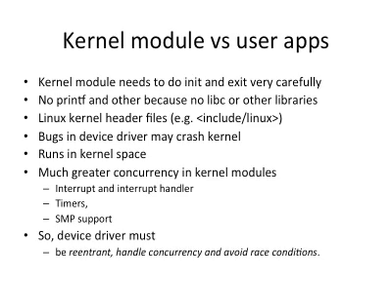So you have to be very careful when you design your init and exit functions. In fact, everywhere in your kernel driver, device driver, Linux kernel module, you have to be careful, especially with space allocation, memory space allocation. We talked about this briefly. There's no printf. The only thing you can do for printing is printk. You will need to include Linux kernel header files, nothing else.